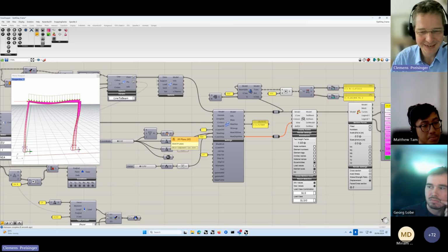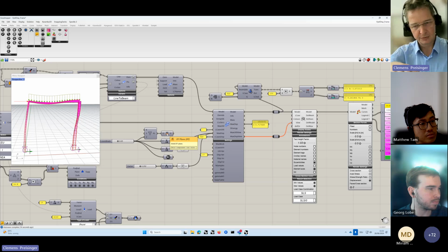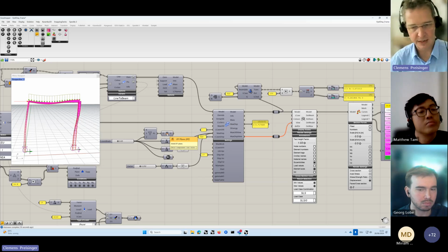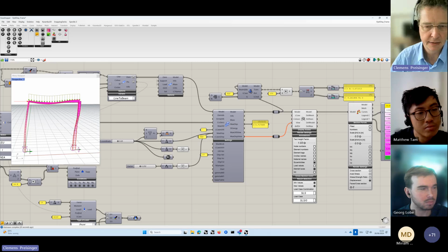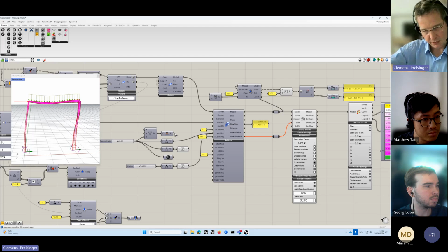You might wonder why or when this is useful. Think, for example, of having a floor slab, and you want to limit the horizontal displacement in the XY plane, for example. And then I can set up a corresponding plane in which I want to limit the resultant displacement.